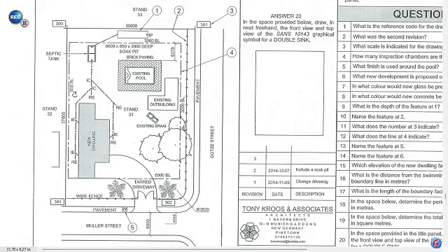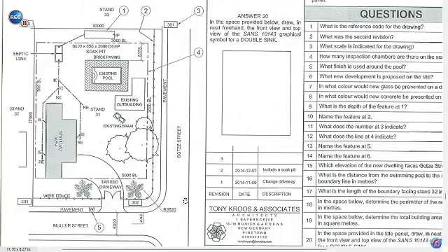The 26.5 meters, which is this distance from here to there, will now have to be multiplied by this distance of 29.8, which is from here to there, and that is going to give you a total building area of 789.7 meters square. 789.7 meters square as your answer to the total building area allowed on the site 31.